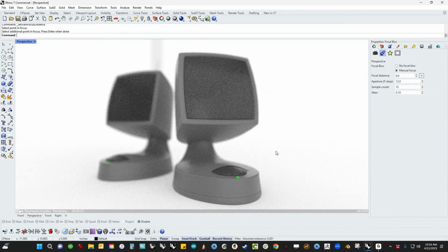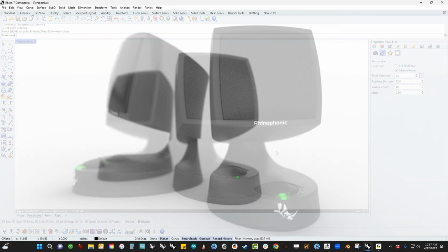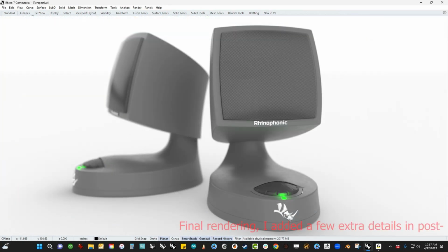Which free software would you recommend to view 3D models? That is a great question. If you go to the Apple iTunes store, you can pick up iRhino for any iOS device, iPad or iPhone, and there's a fabulous viewer. That would be where I would send you for a viewer. If you want to send it to somebody who is using a different software, you need to find out what software they're using. But most 3D modeling softwares use IGES or STEP, so you could send them an IGES or a STEP model. Any other questions?